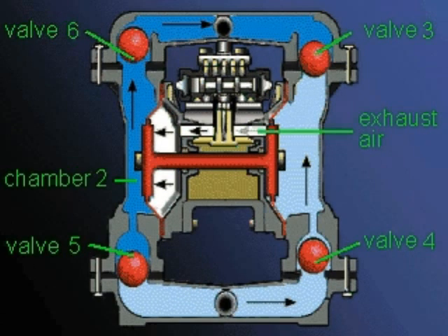To understand this pump, remember that the air valve shifts the air supply to both diaphragms alternately. When air is being supplied to valve chamber 2, both diaphragms move to the left. This forces air out of valve chamber 1 into the exhaust. Valves 4 and 6 are open, and 3 and 5 are closed. Slurry is being pumped from the left chamber.